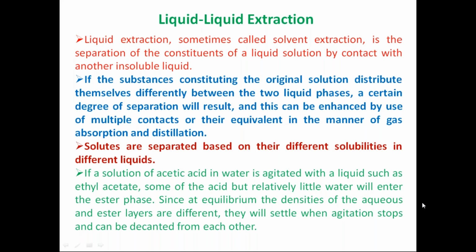So that question arises. For acetic acid and water, if you look at the alpha value, the relative volatility, it is very close to 1. You know what happens if the relative volatility is very close to 1: the equilibrium XY curve is very near to the operating line. That means it requires a larger number of stages. When it requires more stages in a distillation, the fixed cost will be very high.